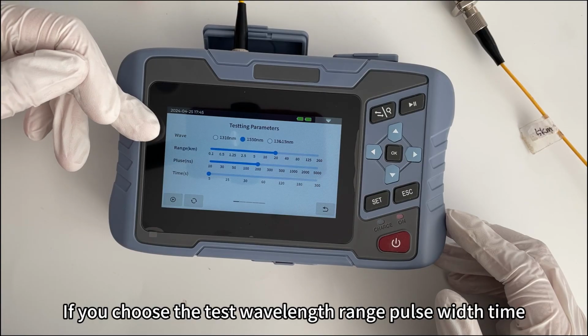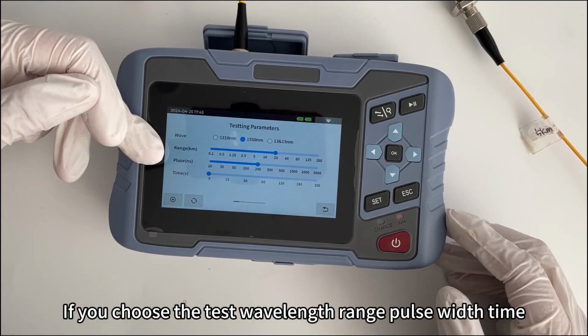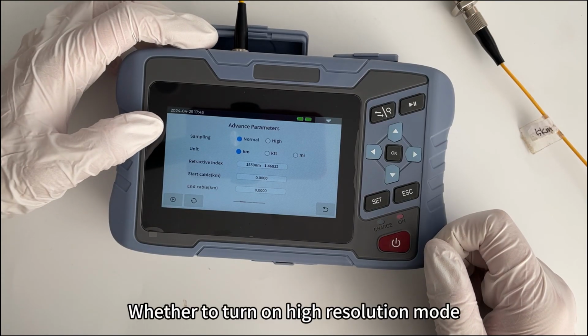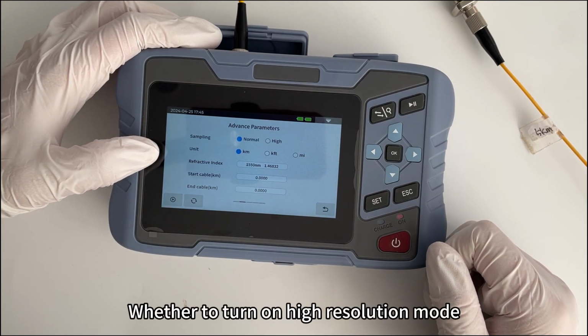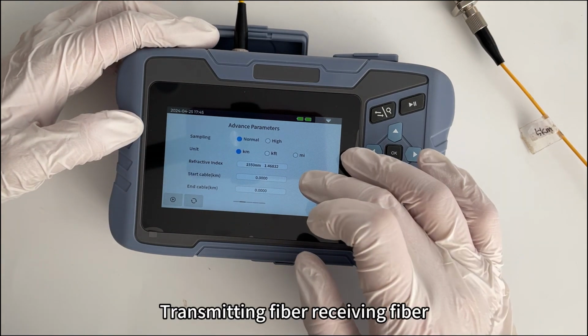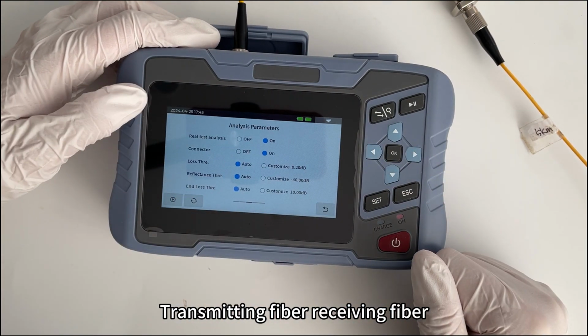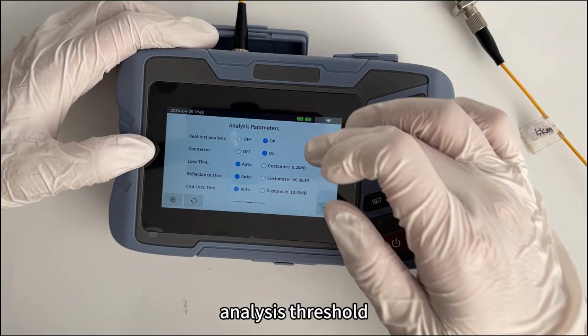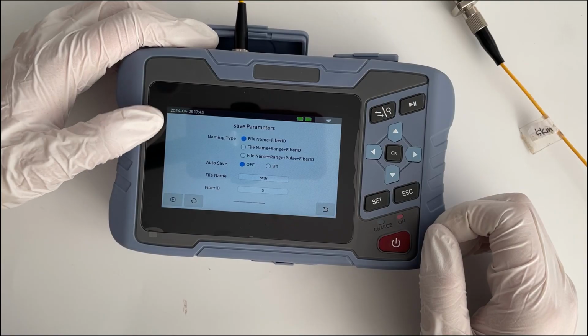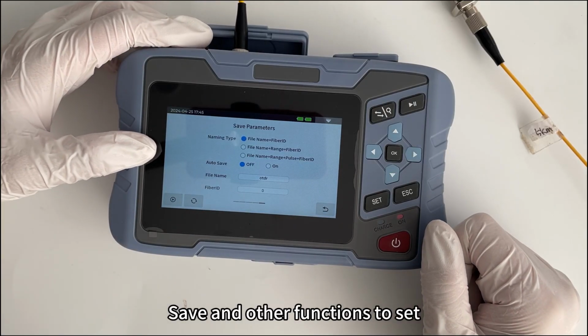If you choose the test wavelength, range, pulse width, time, whether to turn on high resolution mode, optical fiber refractive index, transmitting fiber, receiving fiber, analysis threshold, eligibility criteria, save, and other functions to set.